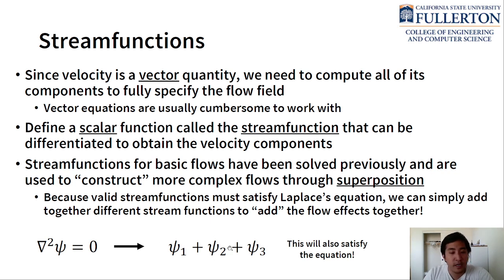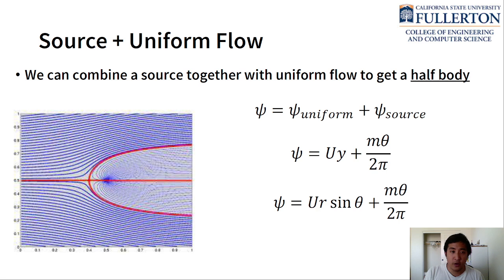Okay, and so you can do this endlessly. Here I have three psi functions that I'm adding together, but you can keep adding more and more. We can leverage this property because we already know some stream functions for basic flows, and so we can add them together and combine them to get more complex flows.